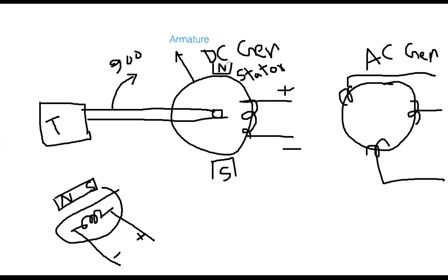And then you see, I have placed North Pole and South Pole to indicate this one. You must need a magnetic field. So therefore, the voltage will be built up here, and that is the DC voltage. In case of the DC generator, it is hardly like 1000 volt. In most cases, it is much lower. The maximum voltage could be 1000 volt. Much more voltage is not produced in that way.